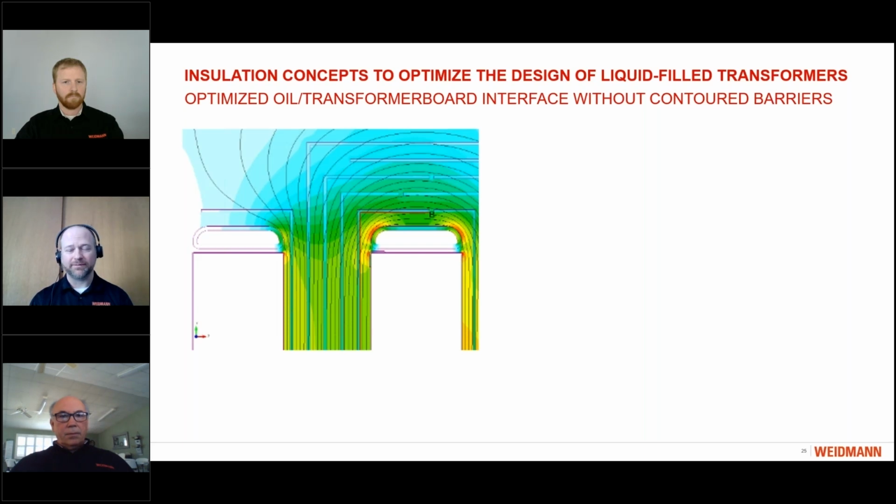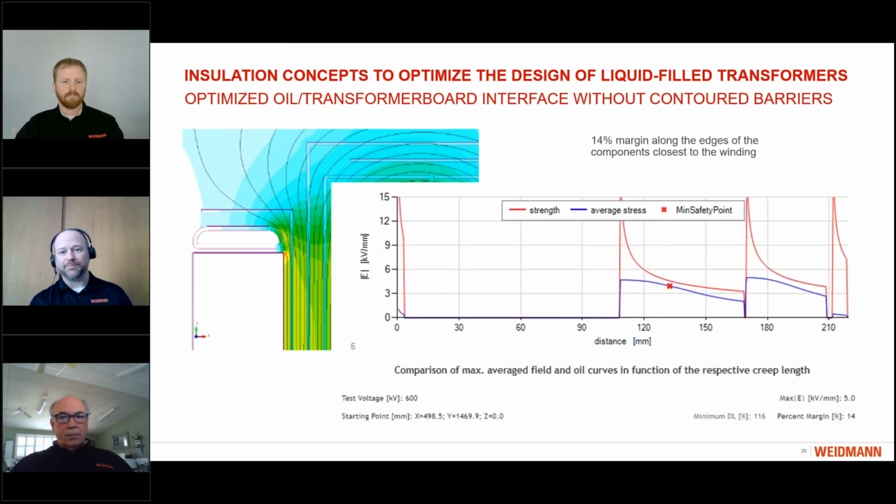And click next. And there we go. So what this is doing is showing us the stress accumulated along those surfaces. To go back a little bit, you can sort of see it in the top left view that's not covered. Wherever those dark black lines, what we call equipotential lines, cross the surface of the insulation, you get a charge accumulation, hence the oil pressboard interface. It's where those two touch. You can see here we can calculate the stress that is accumulated along that interface.